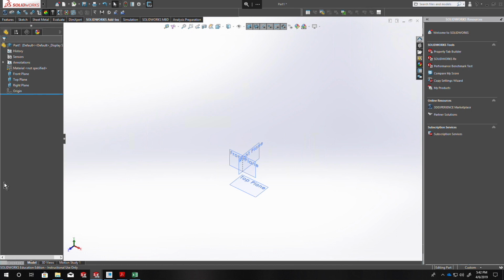Now that you know how to investigate your beams for bending, the next step is to check for shear. The first two examples walk you through how to do that. It's pretty easy to follow, but I'm going to show you how to use Solidworks to check that work. The example in the book uses a S15 by 42.9 beam.